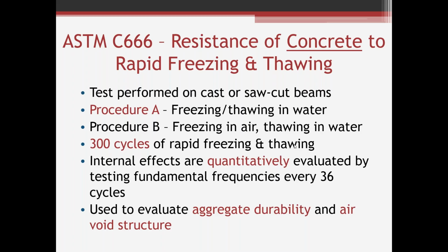As I said, the test is done on concrete, and it evaluates not just the aggregate durability within the concrete, but also the air void structure. When using this test, and I think FAA and Army Corps both specify this test for concrete pavements, you use the aggregate that's specified. I believe it's an aggregate test. But you make up freeze thaw durable concrete that's got air entraining agent in it,